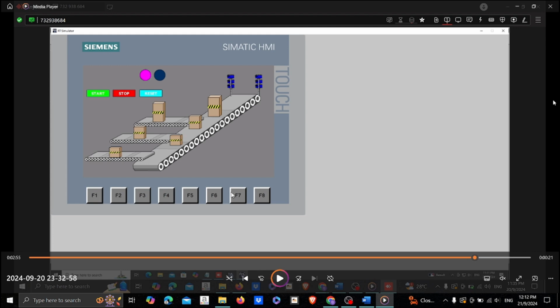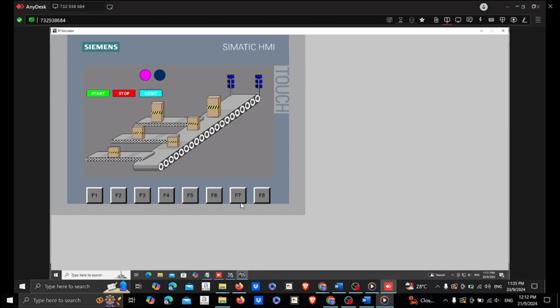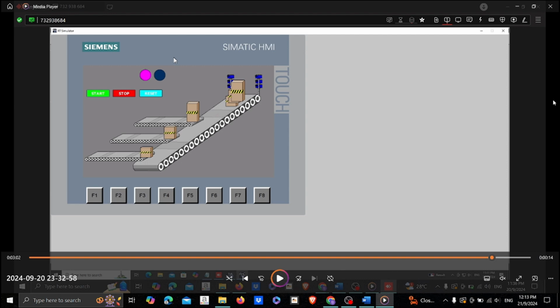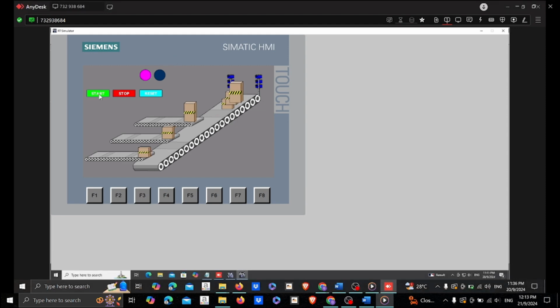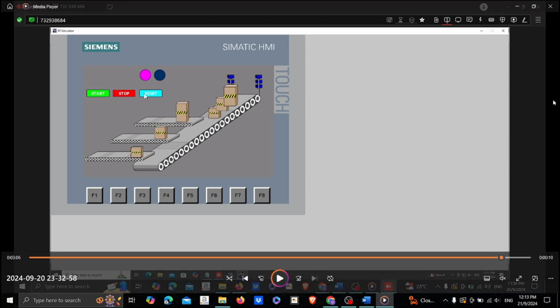For sensor 1, for the high height, it will be detected by the sensor SE1 and then sorted by the pneumatic piston SV1. Then for the box with the medium height, it will be detected by the sensor SE2 and then sorted by the pneumatic piston SV2. And lastly, for the box with the low height, it will be detected by the sensor SE3 and then sorted by the pneumatic piston SV3. The pneumatic pistons SV1, SV2 and SV3 are double acting type solenoid valves.